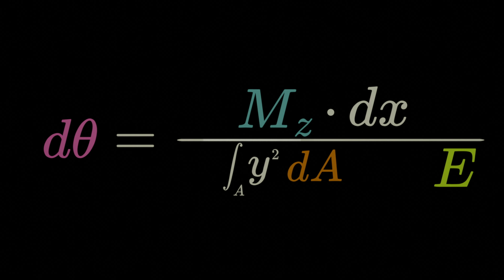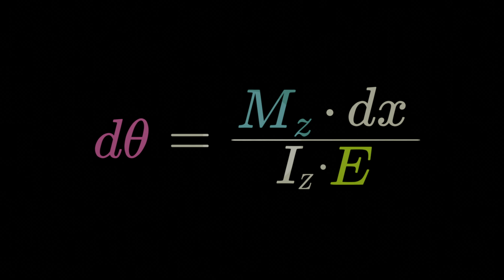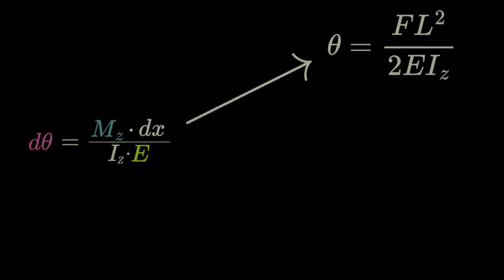We have finally arrived at the formula for the second moment of area, which we can now place into our equation, showing that it does indeed reduce the bending under an applied moment. This equation is quite versatile. Under the point loading condition described at the beginning, we can integrate this equation along our I-beam to arrive at the overall angle of deflection.